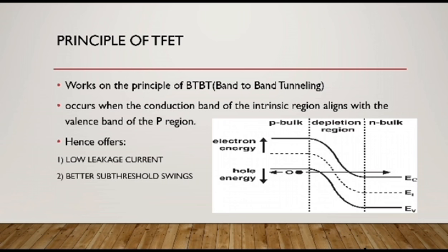Due to the partially filled nano gaps, the dielectric constant in the nano gap reduces. This is due to the presence of air along with the biomolecules, and hence this causes a reduction in the response of the biosensors.